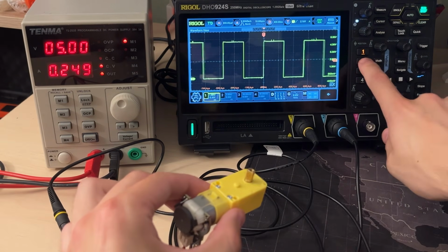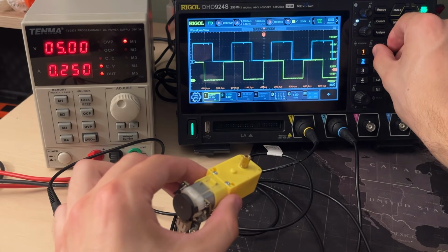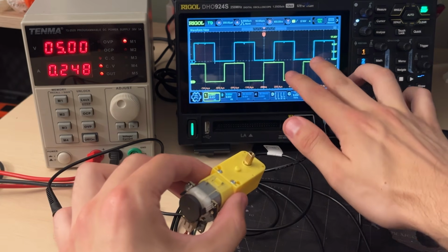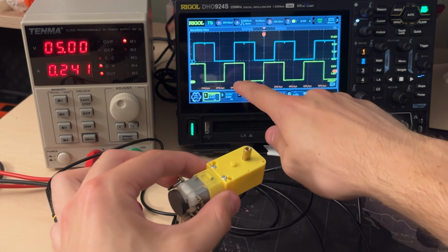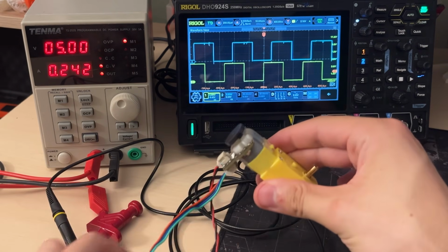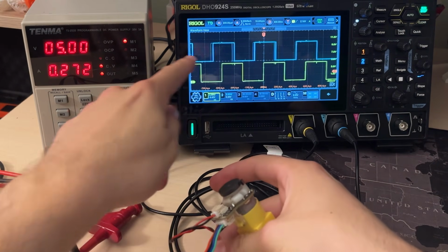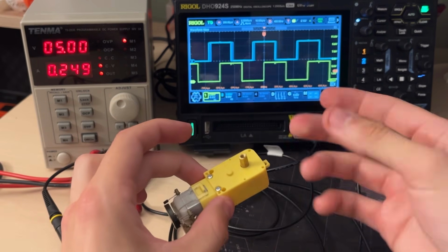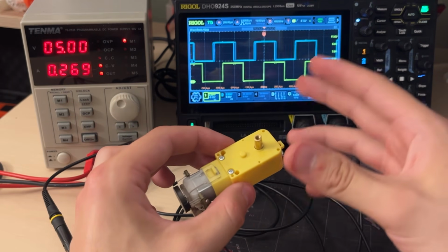Now if we turn on channel 2 as well, and let's just scale them to the same scale like so. If you take a look now, you can see it's the same frequency, but there is a phase shift between these two signals, and that's how we can tell in which direction the motor is spinning. For example, if we look here, you can see the yellow signal, the first signal, is rising first, but now if we switch over the power supply and reverse the polarity, you can see that the blue signal is now going first. And that's how we can tell the direction of spinning from these two. And we're just using one of them to tell the speed at which it is going. So yeah, that would be the motor. So let's go look at the rest of the electronics.